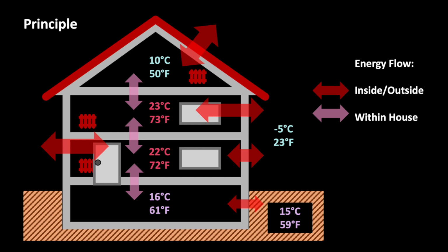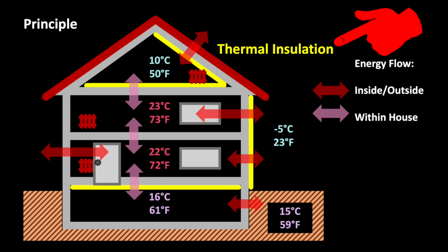Now you might have the idea of playing with the temperatures or checking what advantages thermal insulation could bring to your residential house. To do this, you simulate your house in the current status and in comparison with improved thermal insulation, better windows, etc., that can reduce the energy demand. And in the end, we calculate the heating costs or the air conditioning costs to see the savings effect of our individual measures. Of course, you can then make a cost effectiveness calculation based on the energy costs saved.